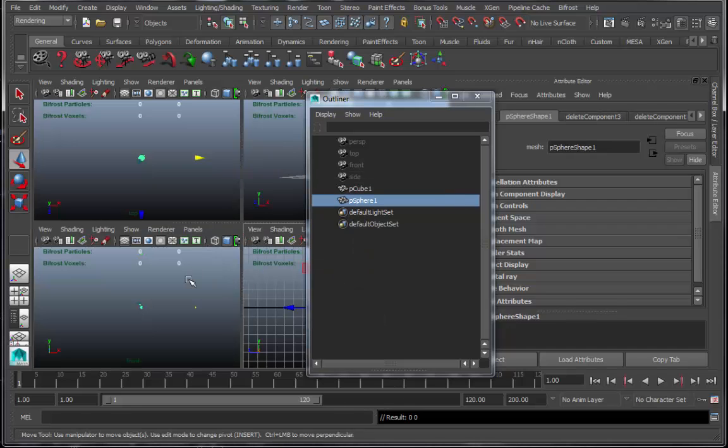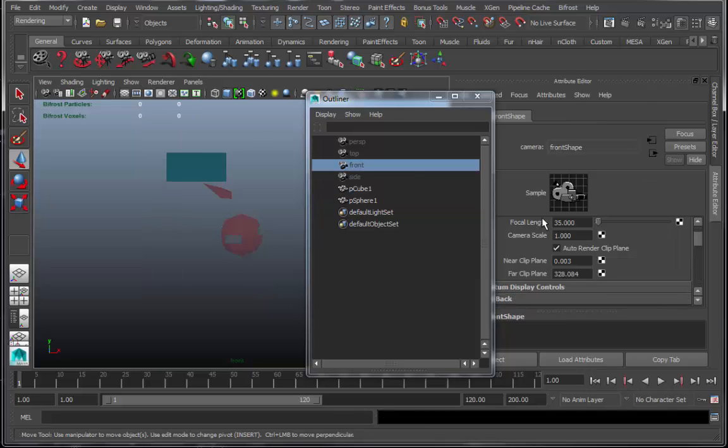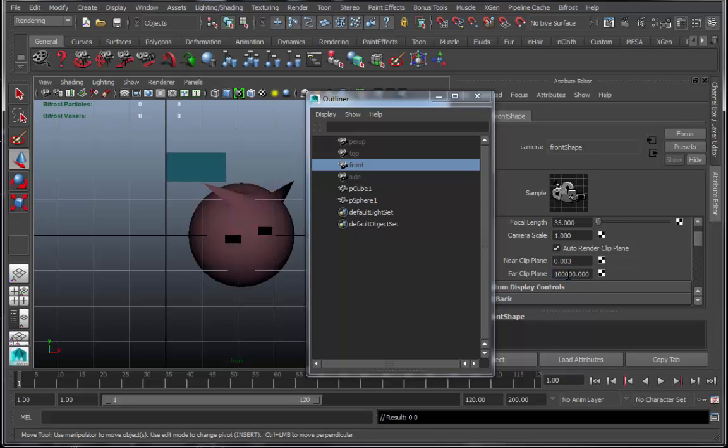So those of you that are having a problem seeing the grid in certain views and/or seeing the object, you can see the clipping plane is actually shearing off what the computer draws. And if you were to grab this camera as well, grab selection and increase that far clipping plane of what it draws, then you'll get the whole of the object.